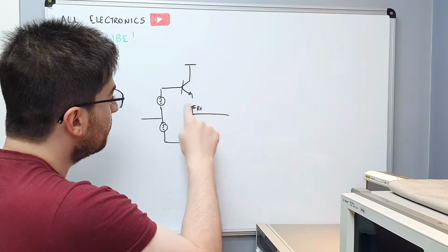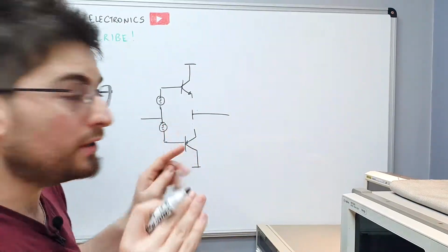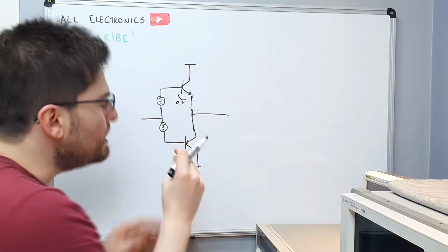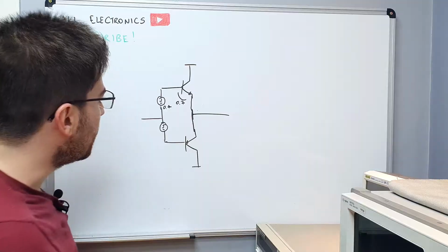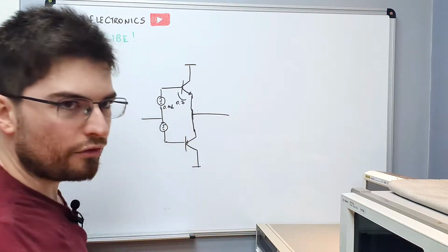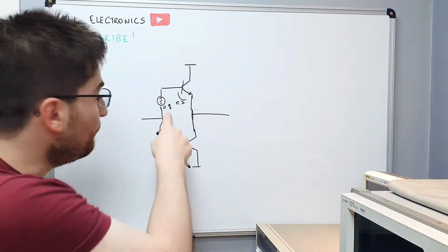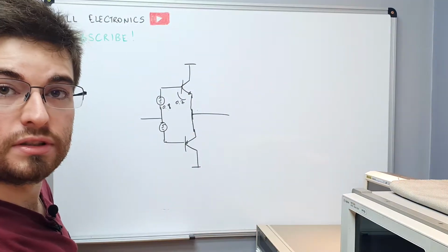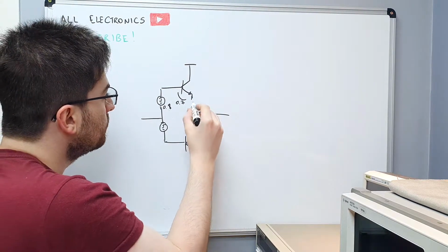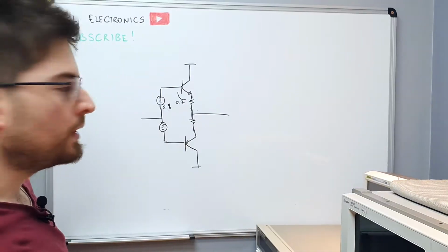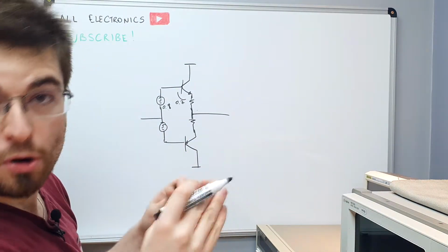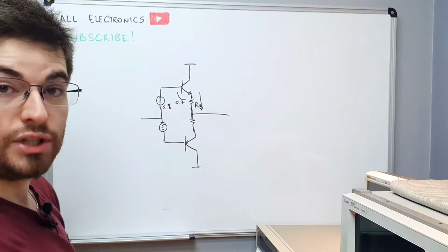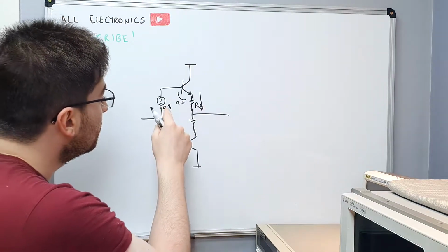Without the resistors, we need a ridiculously precisely controlled voltage here, because think about it. If the voltage drop is 0.7, we need precisely 0.7 volts here. If we put 0.7 to 1 volts, the current will increase a lot. With 0.8 volts, the current will be 10 times bigger here on the emitter. So it's impossible to do this circuit without the resistors here to compensate and stabilize the circuit. With the resistors, it's very easy to program the output bias current, because now we have a constant resistance here and it will generate a linear relationship with the biasing voltage.